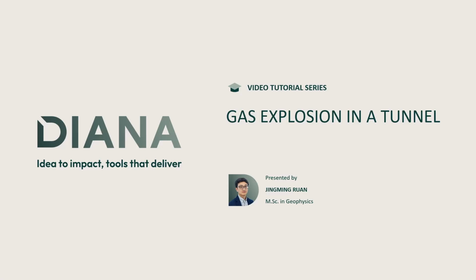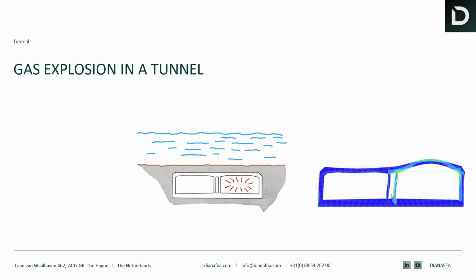Today I'm going to introduce you to a tutorial called Gas Explosion in the Tunnel. In this tutorial we will simulate the scenario where there is a gas explosion on one side of the tunnel. Before we simulate the explosion, we will first calculate the stress state inside the tunnel, taking into account the self-weight of the tunnel and the self-weight of the sand and the hydrostatic pressure of the water above.